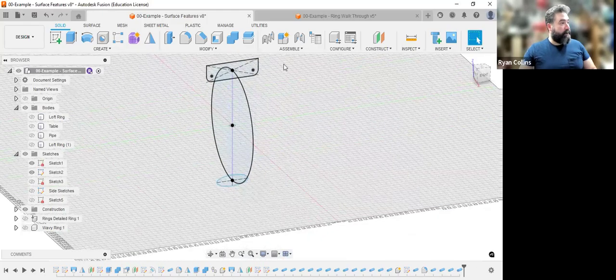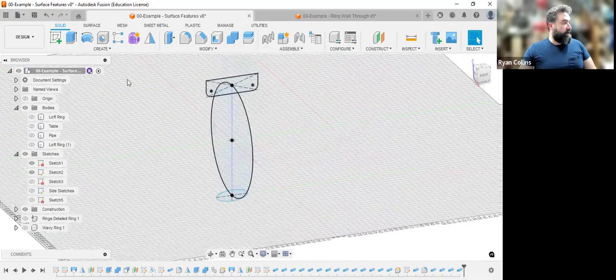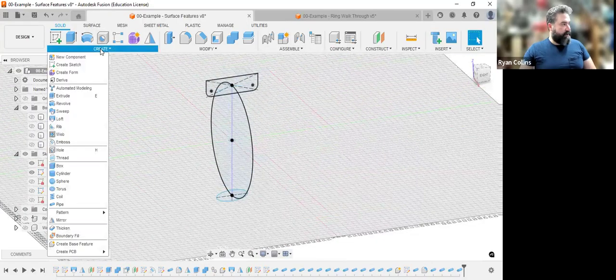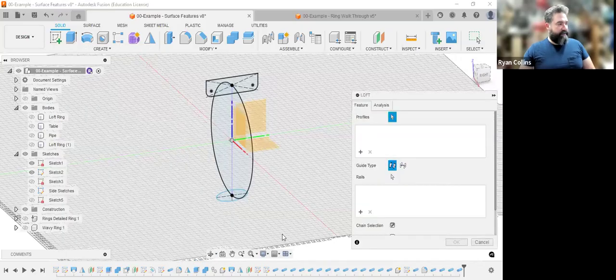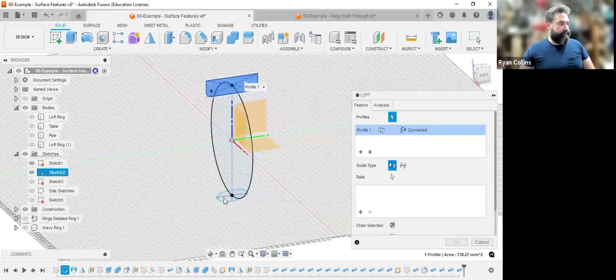And I'm going to just make a quick loft. So just to make a duplicate again, and I'm just using loft because it's the more involved version. Reminding everybody how to use this. I've got my sketches. I have my path, which is the basic ring, the thing that goes around the finger or whatever, the circle, and then my two different sketches, which are perpendicular and on a second sketch. So select the one, select the two.